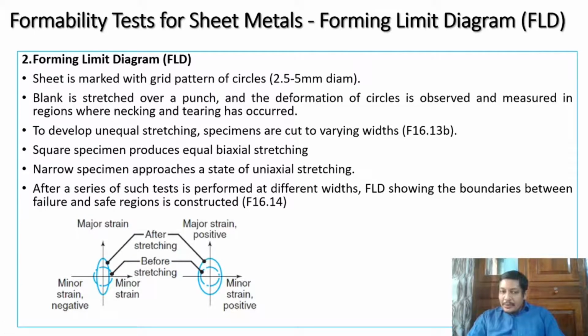And you can see, between this 2.5 and 5, initially there was a wall thickness of somewhere around 1.25 mm existing on one side. As you are loading it, the outside shape will change into an ellipse, inside also, but under a certain condition you can see the wall thickness will become negligible and the material will fail.